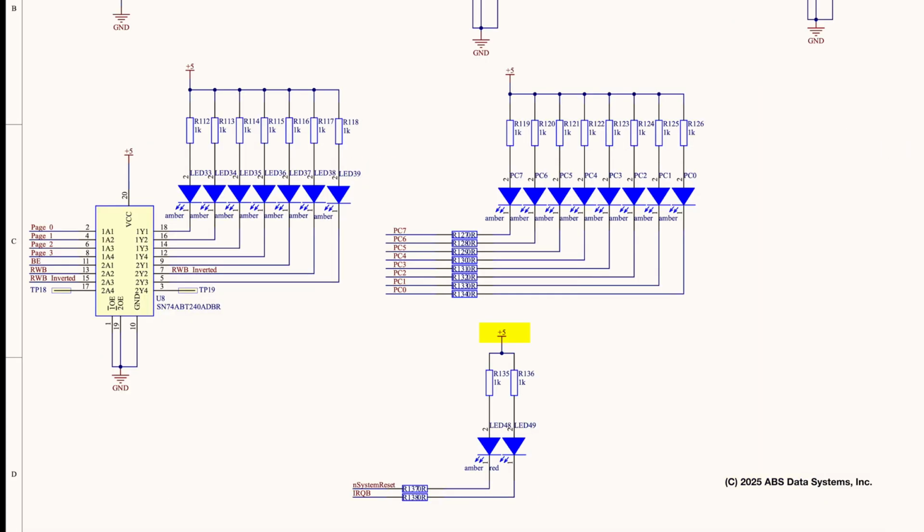I've handled this in hardware. The LED is connected to a 5-volt source through a current limiting resistor. The other end of the LED finds its path to ground in order to complete the circuit. Sometimes that path is when the digital signal is low. Other times, the active state is high. In this case, I use an inverter to provide the path to ground.